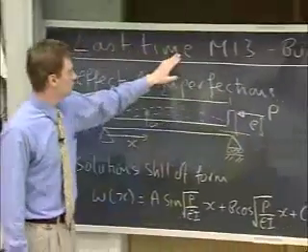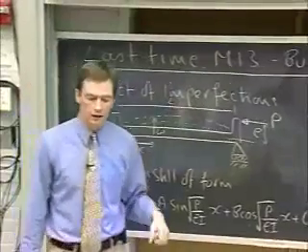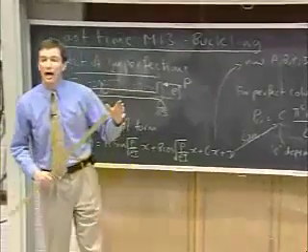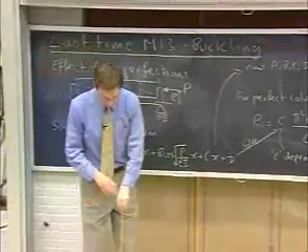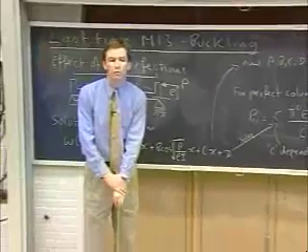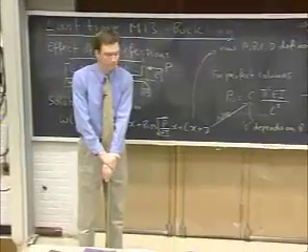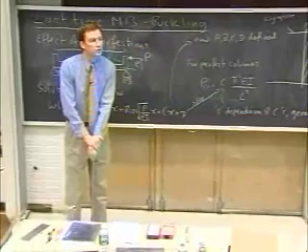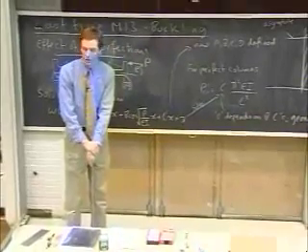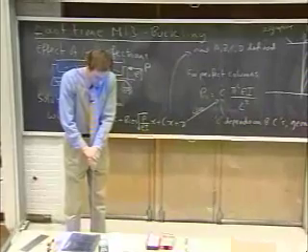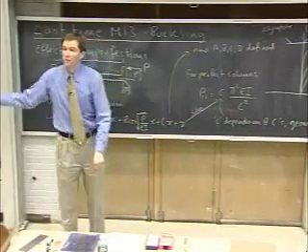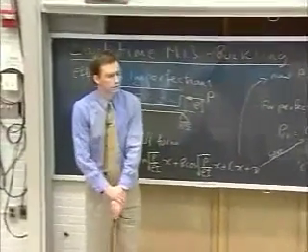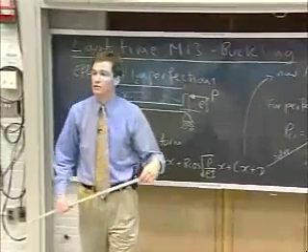Last time we concluded talking about buckling, and this is also concluding our treatment of structural analysis. So buckling is one of many examples of an elastic instability, where if we axially load, in the simple case we're considering an initially nearly straight column, it loads up elastically and then bang, it goes unstable on us. If this was a structure, it would represent a dramatic loss of load carrying capacity.